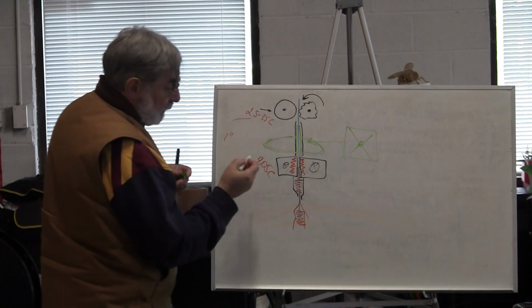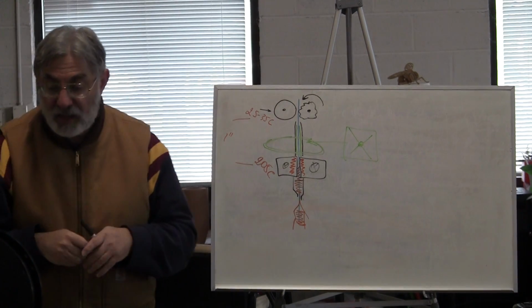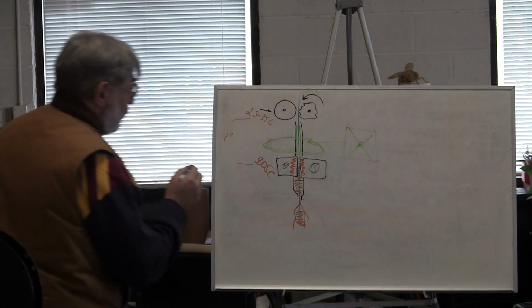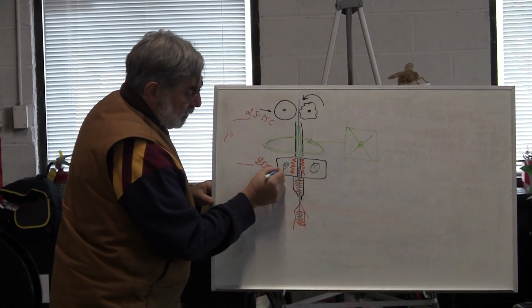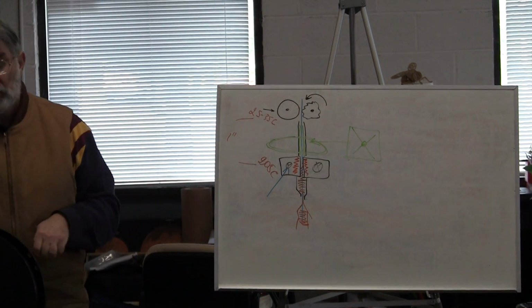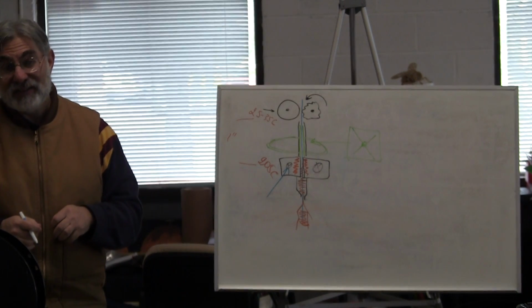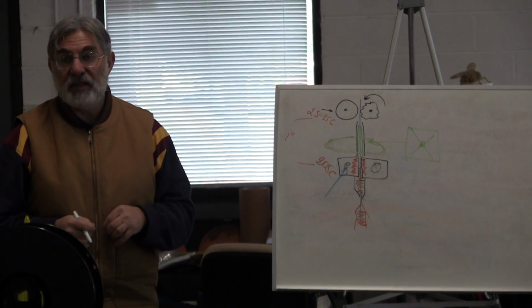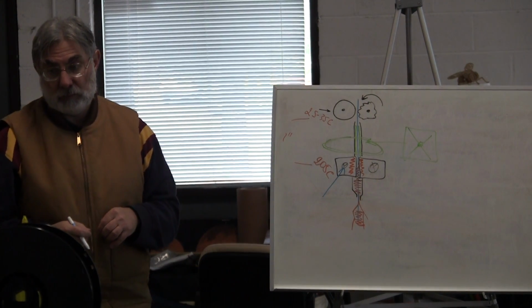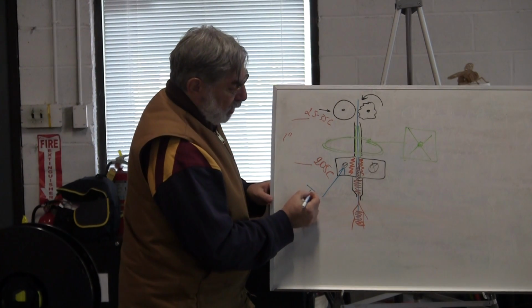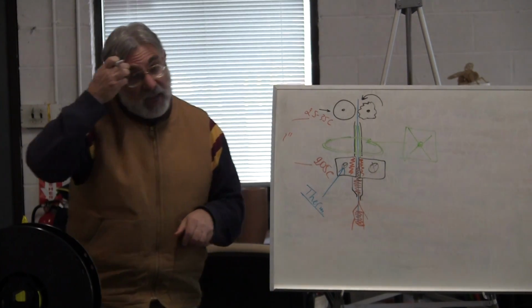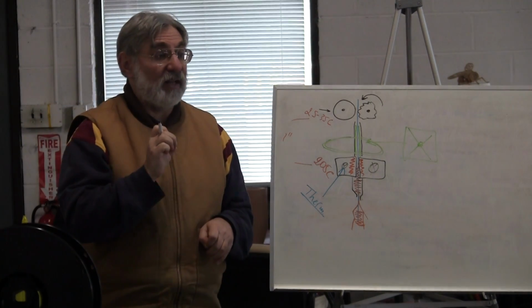One of the things you will learn is that here are the parts that you will end up replacing on your machine on a regular basis. You will replace thermistors. On the average, the first couple of months you won't need to, but after a few months of operation you'll be replacing them at least once a month. Simply because they burn out. They're running close to their top rated temperature. That and they are very fragile mechanically.